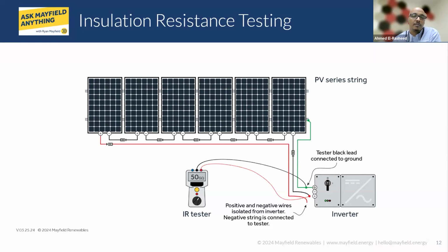So what an installation tester is there to do is, with low power, so it's not damaging the asset, it will put electrical pressure, which is a higher voltage, at least at the operating level voltage or a little higher is better, to put some pressure within the pipes, so to speak, of the flow of electricity. And if there is a leak, then the meter itself will actually show that the current is not all finding its way back. It's leaking somewhere.